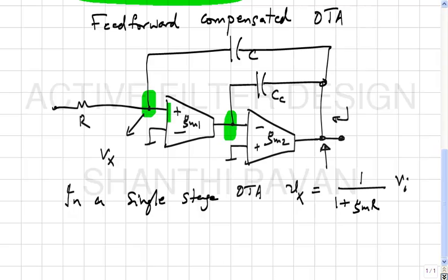The voltage across the integrating capacitor of the integrator and the compensating capacitor Cc must be about the same, correct? If the voltages across the two are the same, what comment can you make about this current versus this current?